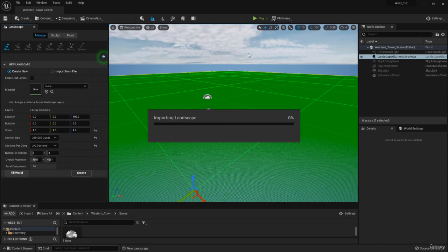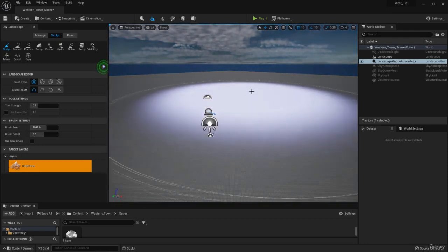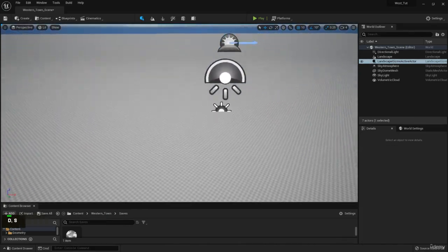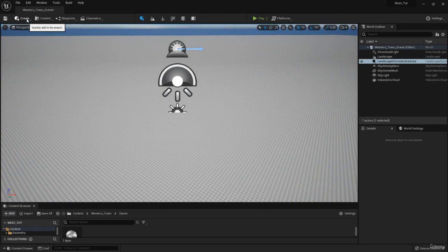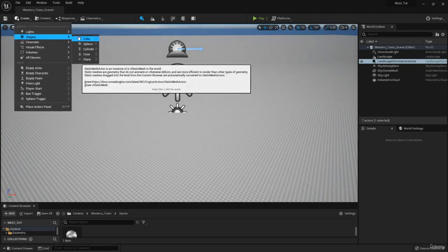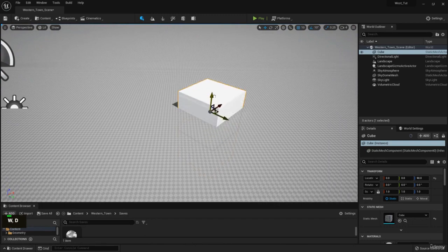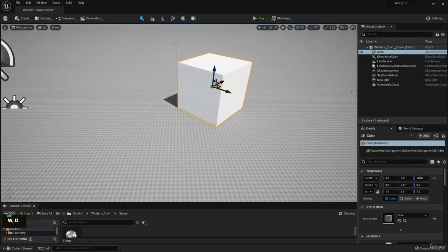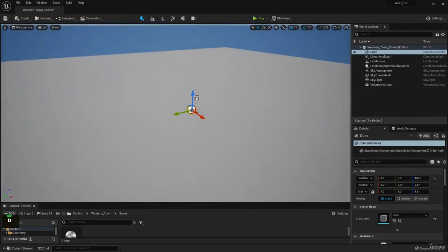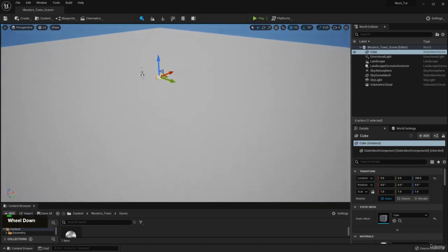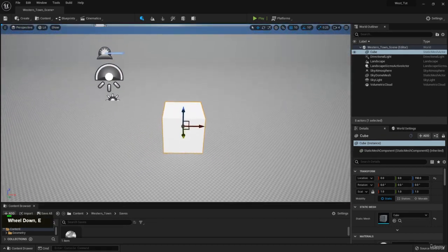You then go ahead and press create, and that will create our terrain over here. There we go. And at this point you can see that you can sculpt, but we can just close this. So this is our terrain. Now, as I said, I was curious how big this actually is. So if we go to create, shapes, and create a cube, and then in your cube, if you press the little button next to your transform, you can reset it to 0, 0, 0. So this cube is 1 meter by 1 meter by 1 meter. That's very good because this will also be our base scale. So as you can see, it looks like our terrain might actually be a little bit small. But for now, that does not matter.